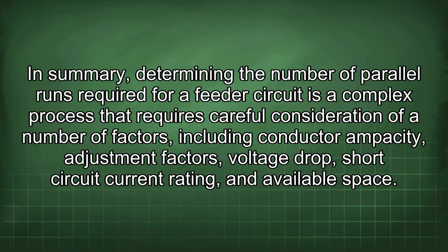In summary, determining the number of parallel runs required for a feeder circuit is a complex process that requires careful consideration of a number of factors, including conductor ampacity, adjustment factors, voltage drop, short circuit current rating, and available space.